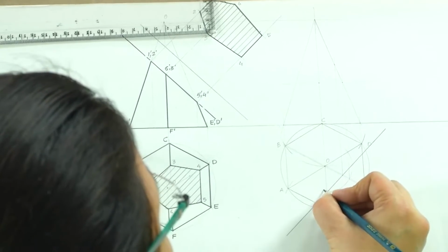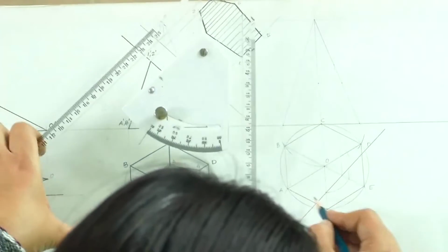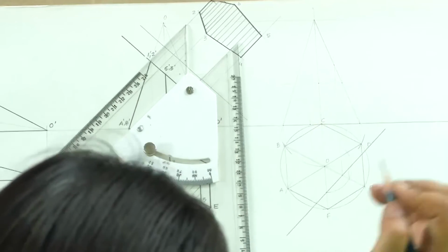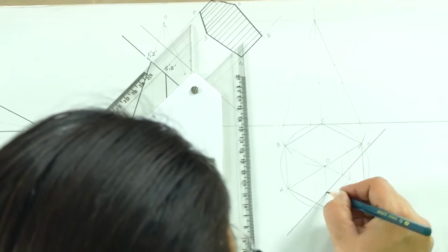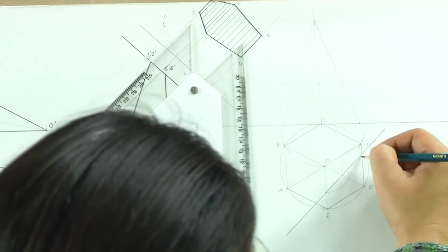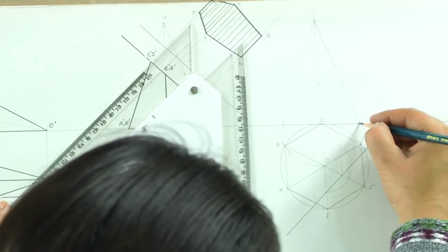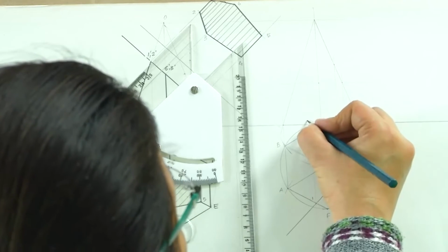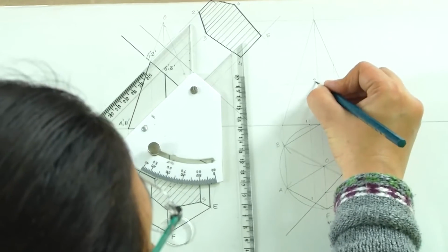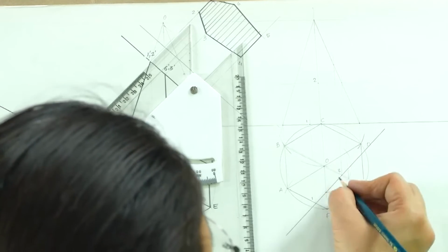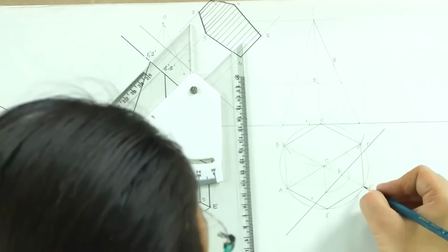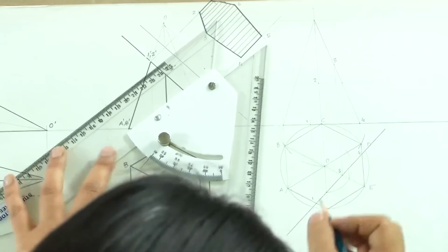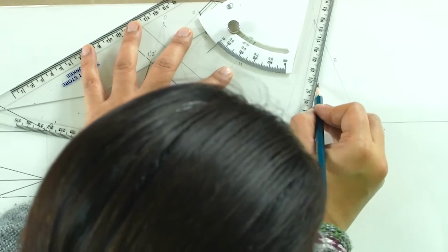So, I get this point, and then in the base which is AF, I get this point which is here. So, I get this 1, 2, 3 and the fourth point is in DE, which is again here. So, what do I get? I get 4 points here: 1 which is here, 2 which is on OF which is here, 3 which is on OE which is here, and this point on DE which is the point 4 which is here. So, now let me join these points for this section.